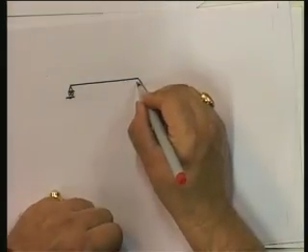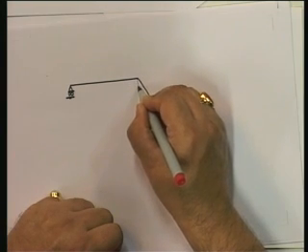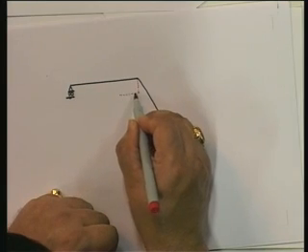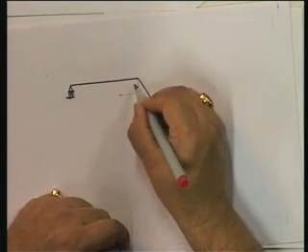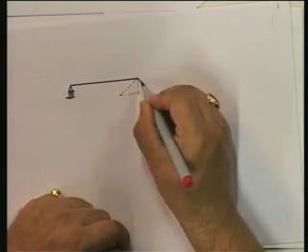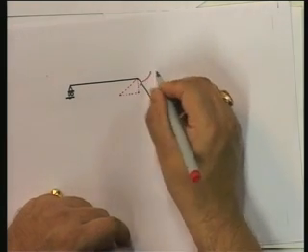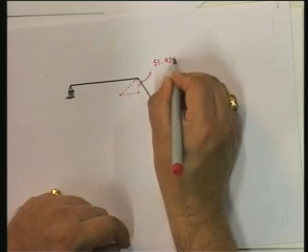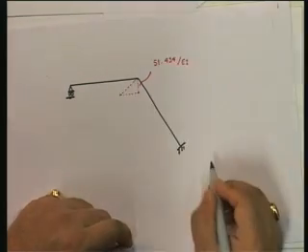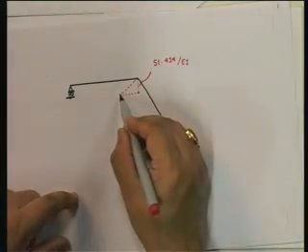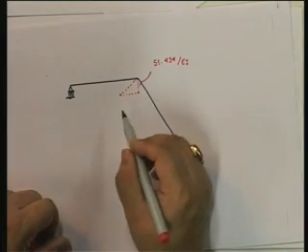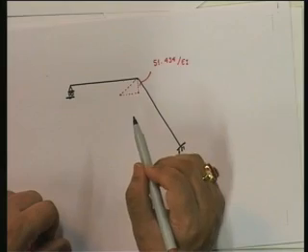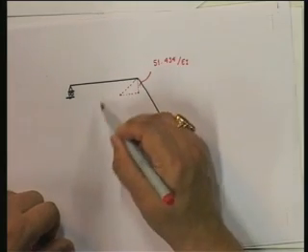So this vertical, it's actually moved down. In other words, it can't move down, so it will have to move this way also. So this point has actually come here, where the vertical displacement is equal to 51.434 upon EI. From that we can find out this displacement, and furthermore this has rotated in an anti-clockwise manner. In other words, it's gone this way.